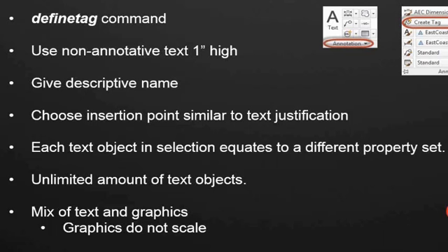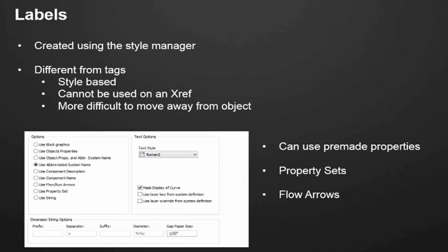So if you create a box around a tag that is 3 letters long and you change your annotation scale, that box and that tag will scale together correctly, but now all of a sudden your text is no longer 2 characters, it becomes 10 characters. It will expand outside the boundaries of that box, because that box will only scale with your annotation. It will not scale with your text size. And we can look at an example of that back here in AutoCAD.